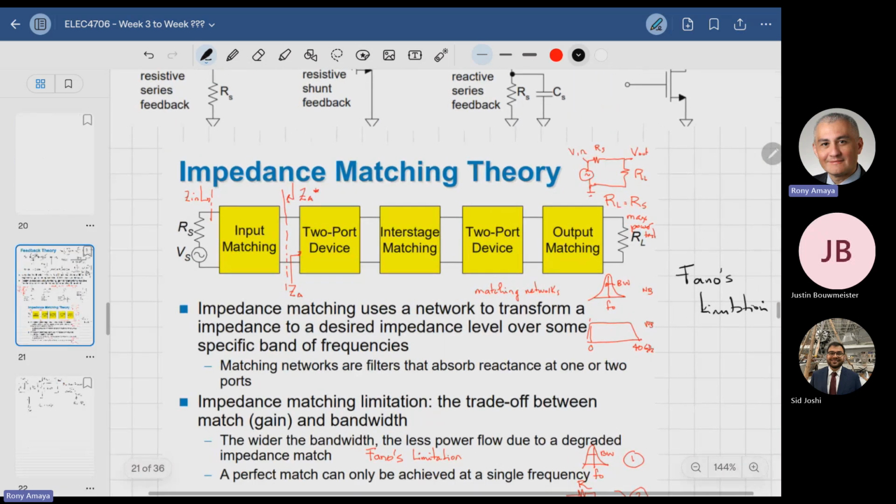So in a typical network system, you have a source, P_S, with a source impedance, R_S, trying to send a signal down to an R_L or a load. This is actually a very simple network. It would actually be composed of multiple stages. Two-port devices simply means something that has an input and an output. I've shown you as two ports here, but really the bottom one is the ground return. So you have an input and you have an output.